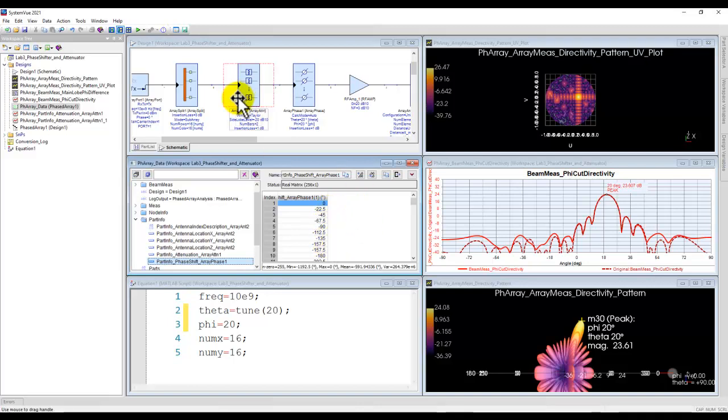All right, so now the last thing we need to think about is that I may not design these components. These components I might be buying from a certain vendor. So how can I bring the real world vendor's measurement data into my system design so that I can get an accurate representation of what's going to happen, how the real world part imperfections matter? The attenuator will have amplitude settability error.